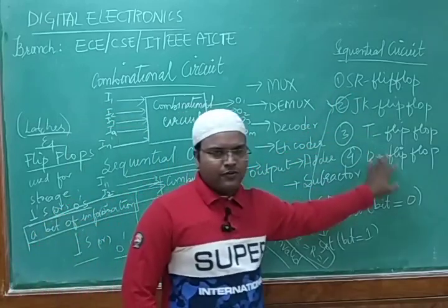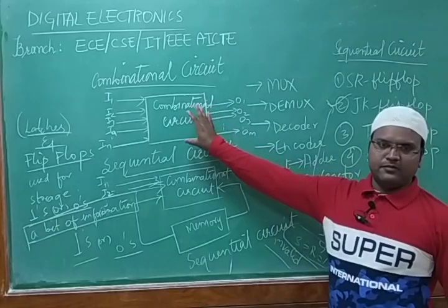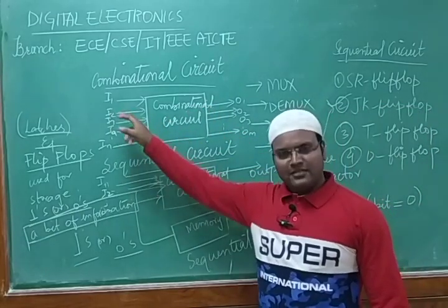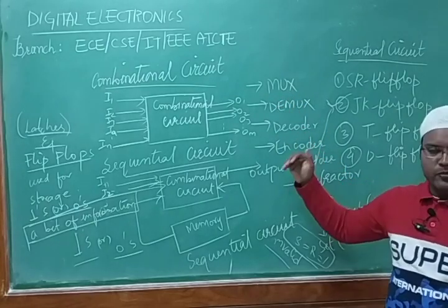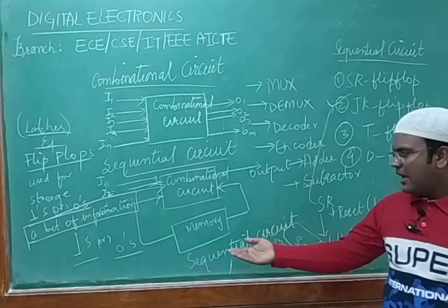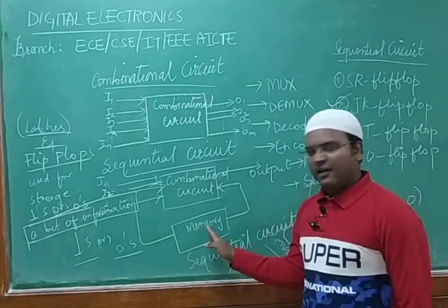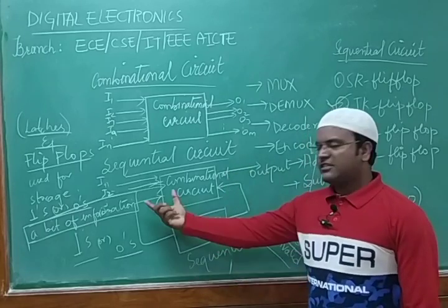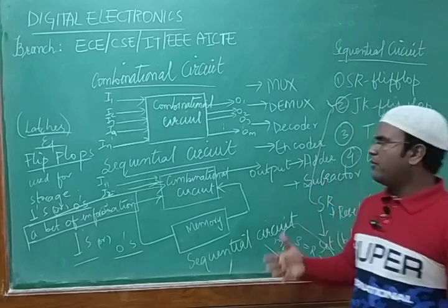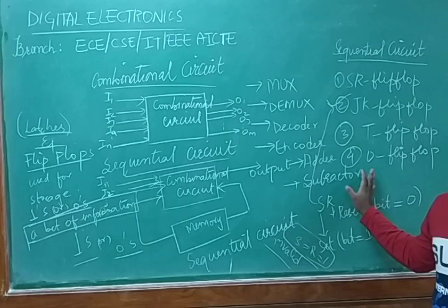Similarly here also, first thing we will do is write its block diagram. We will draw one block and give inputs as J and K, S and R. Then we write the outputs. Here the outputs are Q, capital Q, Q and Q bar, present state and next state, because as I'm saying, memory means it can have the previous state, the present state and the next state, right? They can have 3 states. How it depends on those 3 states, we are also going to see in the flip-flops, because flip-flops are the design of memory elements.